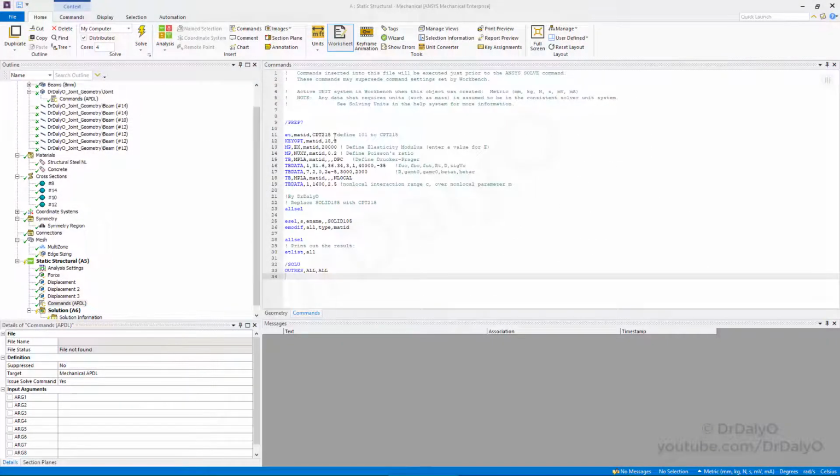Now, coming back to our command, we can see that we're defining the CPT element over here. We are determining here the elastic modulus, the Poisson ratio. Here we're saying to use the Drucker-Prager model, and then here are the locations for the table data for the parameters such as FUC, FBC, FUT, etc. And then the same thing here, this is a continuation of the parameters that you need to input. And then finally, as well as the non-local parameters over here, which are the parameters C and M.